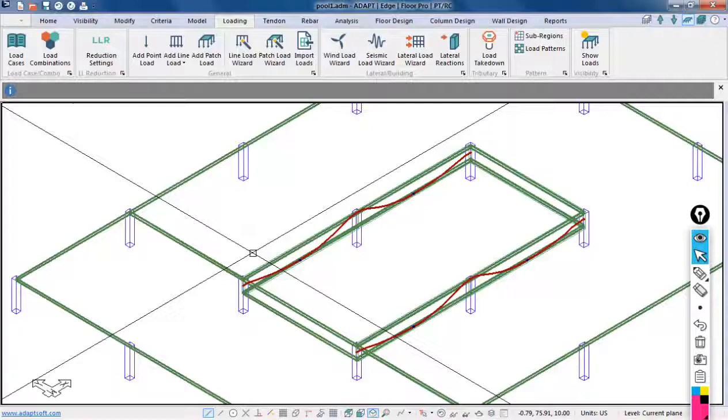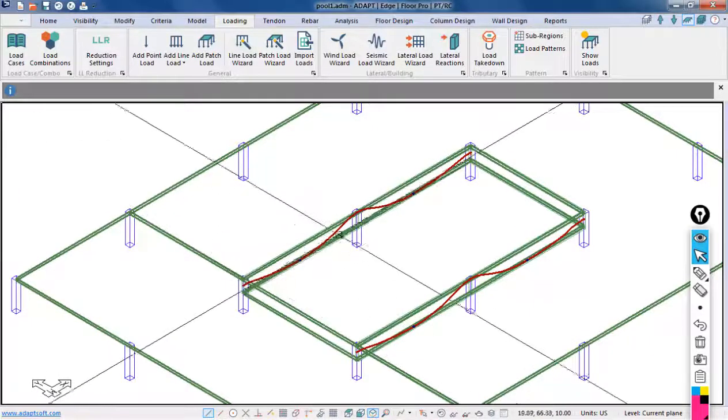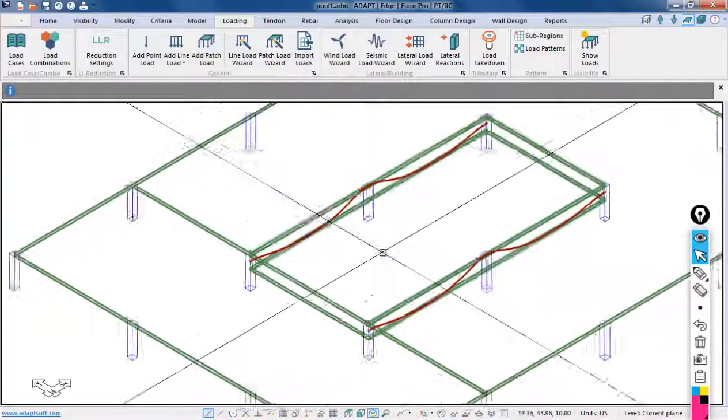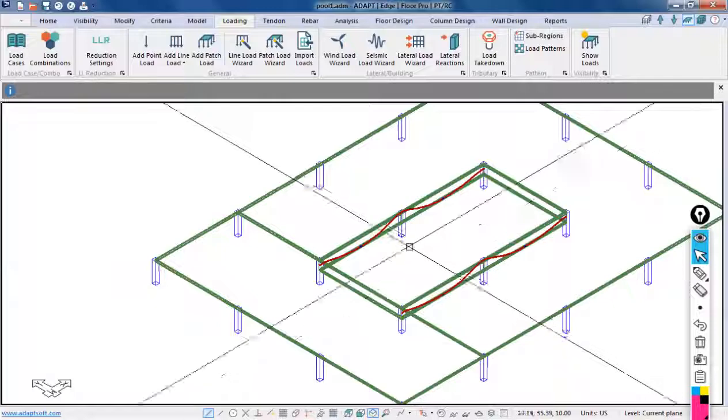In addition to that, because the tendon exits the slab and it's not technically recognized within the wall, you essentially are forced to use an effective force method for assuming the post-tensioning in those members.